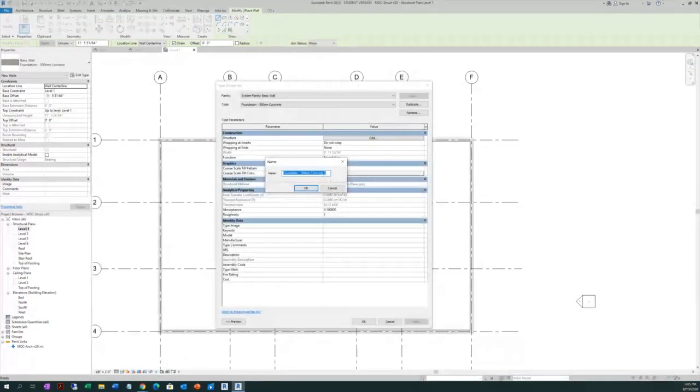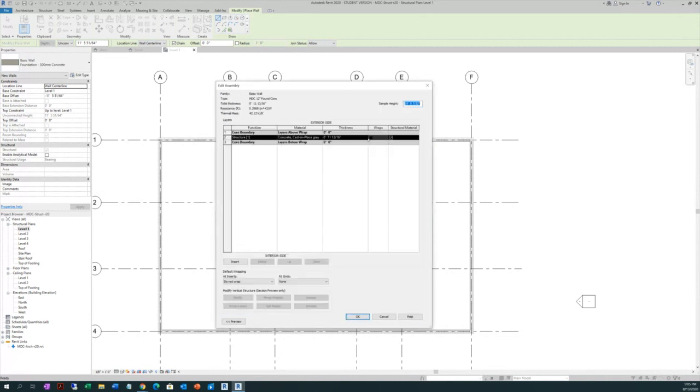Okay, no problem. I'm going to go ahead and name it BC 12 inches concrete or foundation wall. So I know it's my foundation, 12 inches foundation. Or just put an abbreviation, foundation concrete. That's it. Now make sure on my assembly it is, yes, 12 inches, correct? It's concrete cast in place grade.